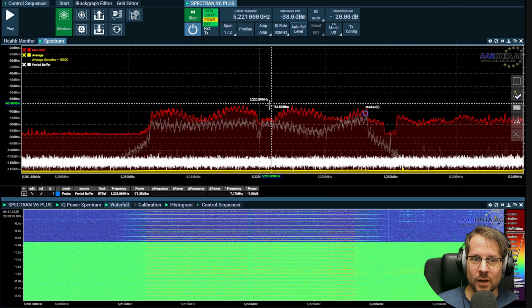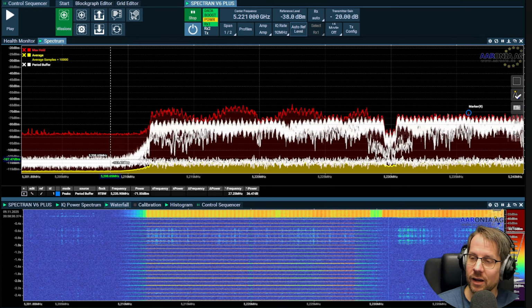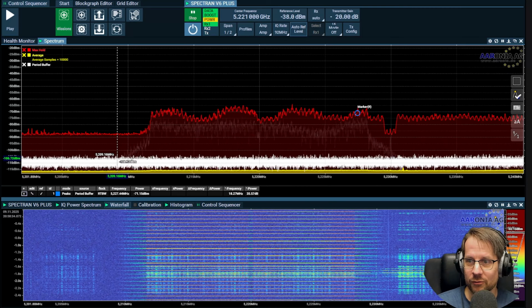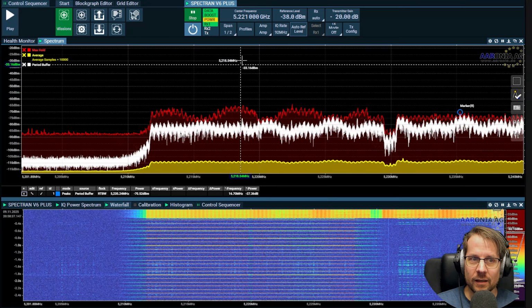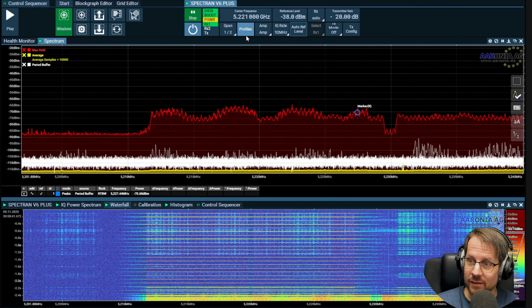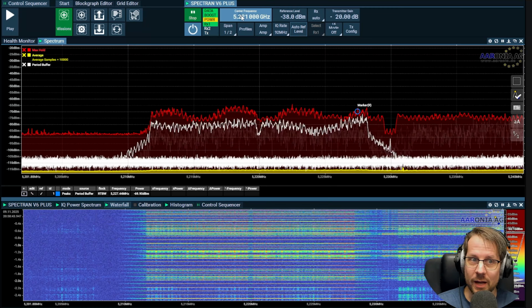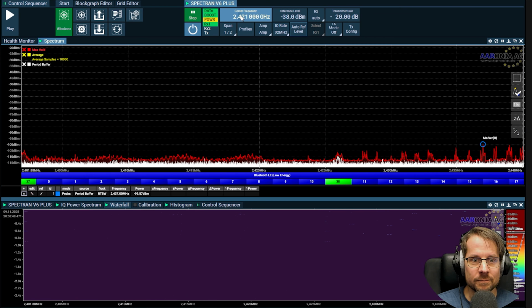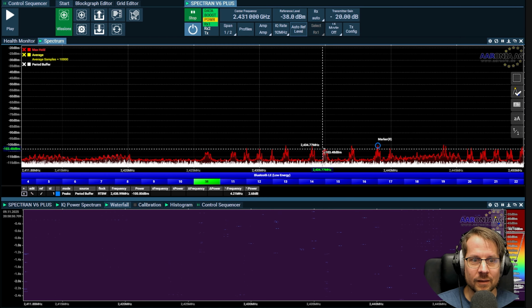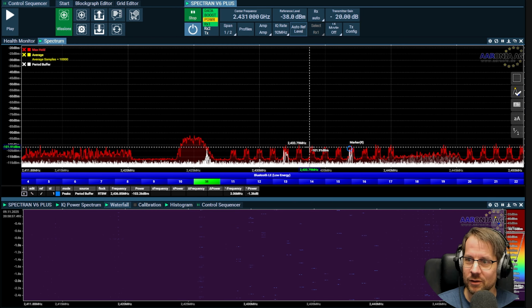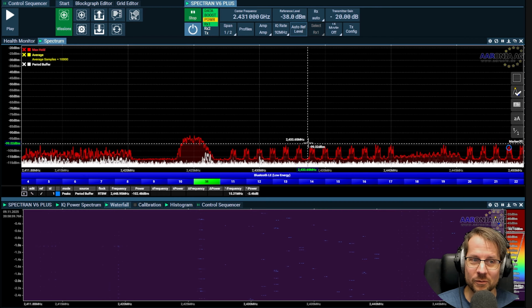So with one amp, minus 38 comes from my Wi-Fi and those levels around minus 100, absolutely perfect, right? And then what about this signal? This is a bandpass filter, right? This is a 5 GHz bandpass filter. So what do you think 2.4 looks like? Up to minus 104 dBm for Bluetooth. That is low, right?